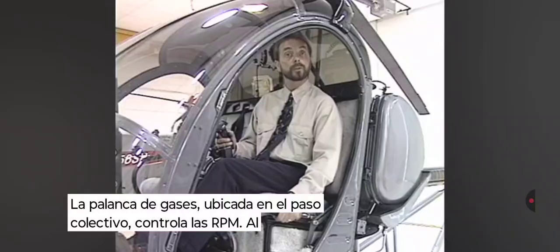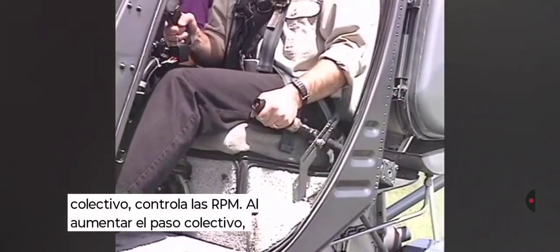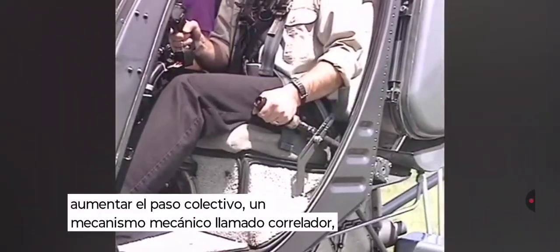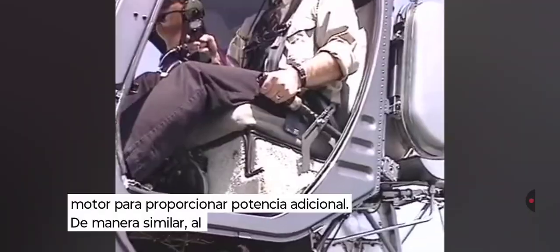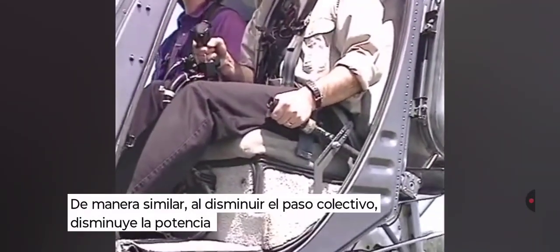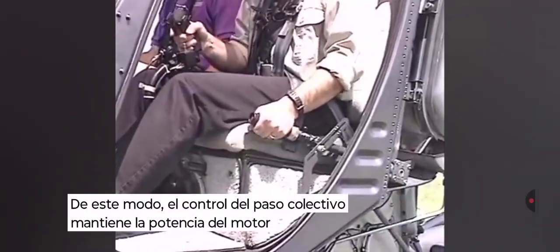The throttle is located on the collective and controls RPM. As collective pitch is increased, a mechanical linkage called the correlator, or in some helicopters an electronic governor, increases the throttle automatically to provide additional engine power. Similarly, as the collective is decreased, the throttle is decreased. In this sense, the collective control maintains desired engine power.